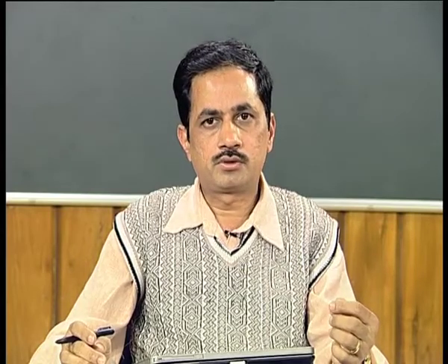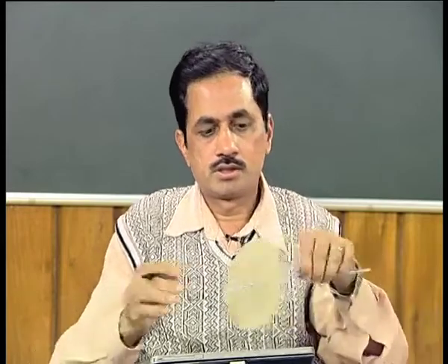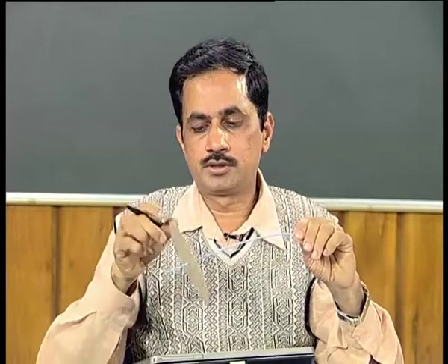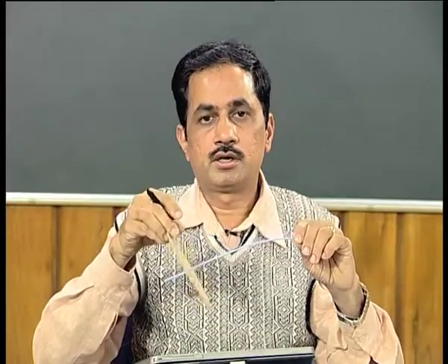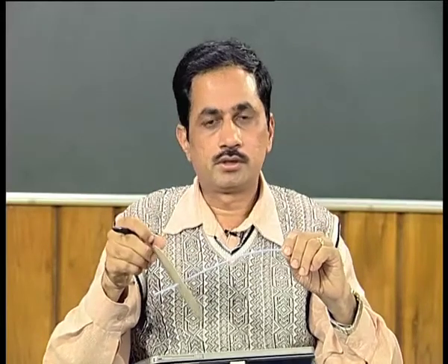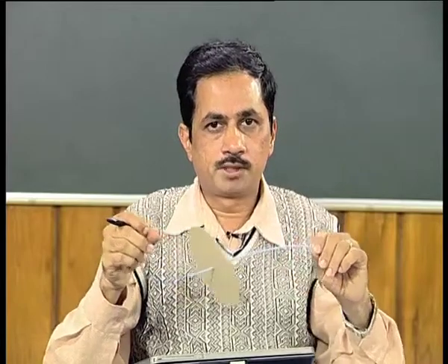Now, we can get the angular momentum of the disc, because this particular disc is tilting about its diameter. So, for the angular momentum calculation we need to consider ID, the diametral mass moment of inertia, and we will be multiplying it with this velocity which we obtained.